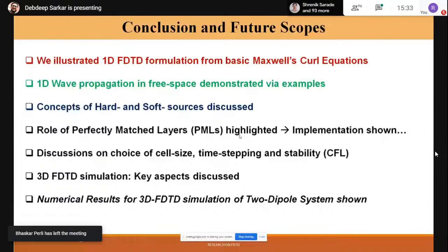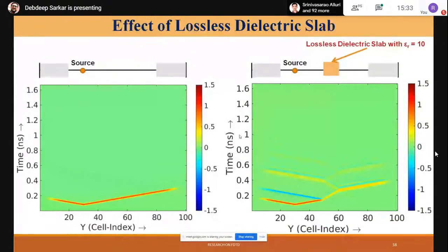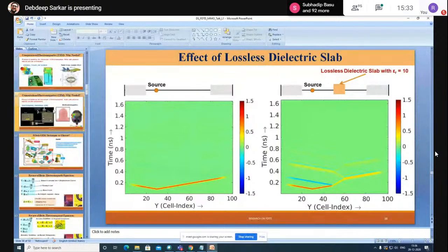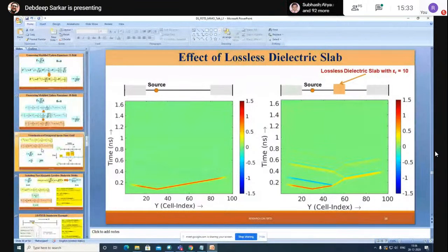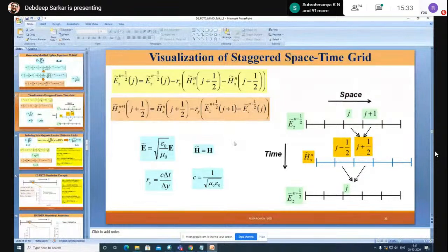So yeah, I think one key thing is in the FDM, you can see from the name itself, the way I understood, that we have this time domain, time marching kind of thing over there. So that is one key thing. Another very important thing, let me go back to some of the formulations a little bit. I will just quickly go to that slide to make my case stronger. So yeah, let's say we have this thing. In this case, it is completely explicit what they're trying to mean, that we do not have to go for any matrix inversion kind of thing over here. So it is an explicit solver.